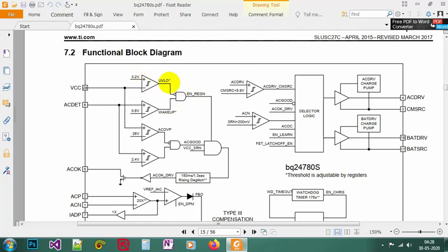And now we are getting a low output from this Schmitt trigger. This is a Schmitt trigger, it's just like a comparator. So here you will get 0. But after the NOT gate it will become high. Let me write here, it is 1. Right, and this is an AND gate. We can call it an AND gate because the NOT is connected before the AND gate.